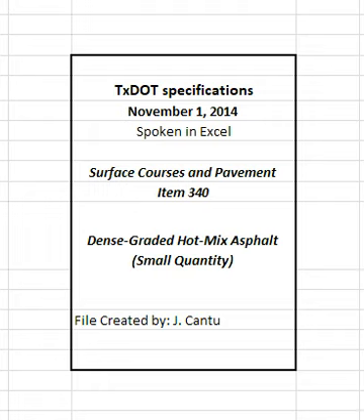Do not use department or contractor-owned RAP contaminated with dirt or other objectionable materials. Do not use department or contractor-owned RAP if the decantation value exceeds 5% and the plasticity index is greater than 8. Test the stockpiled RAP for decantation in accordance with TEX 406A, Part I. Determine the plasticity index in accordance with TEX 106E if the decantation value exceeds 5%. The decantation and plasticity index requirements do not apply to RAP samples with asphalt removed by extraction or ignition.